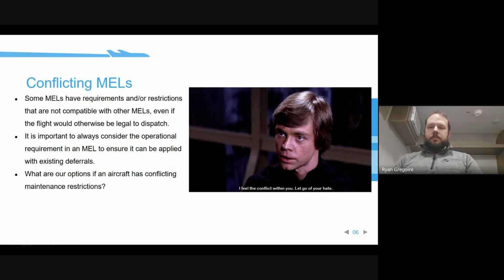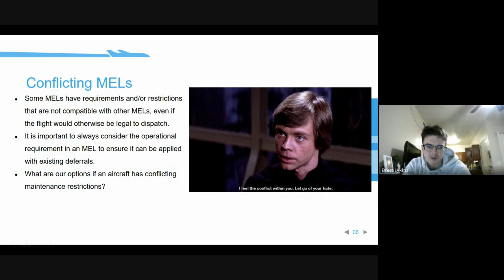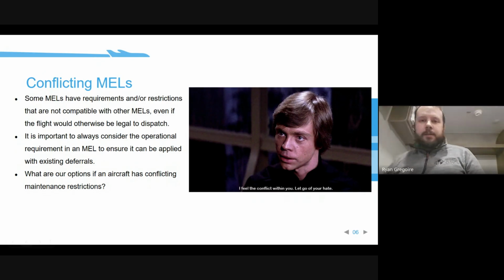Brett: Would it be possible to try and get the issue resolved with a mechanic or something? Yep. So Brett, and I think someone put in chat as well, on the same kind of theme, give maintenance time to fix the airplane. If we could get one of the issues resolved, either the anti-skid system or the thrust reverser, we no longer have that conflict in the MEL, and we can now legally dispatch.